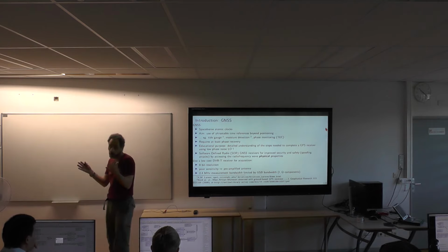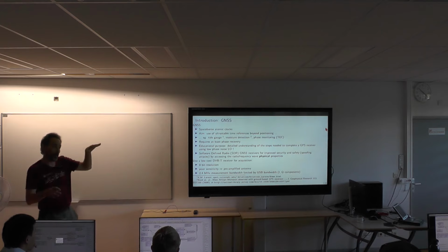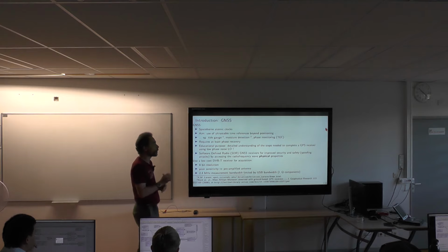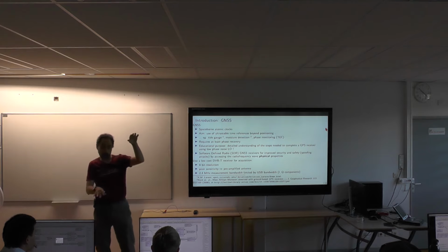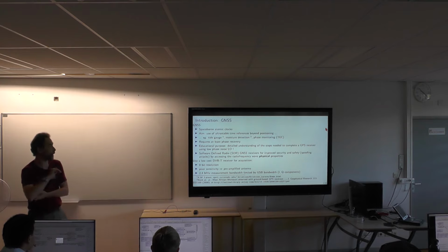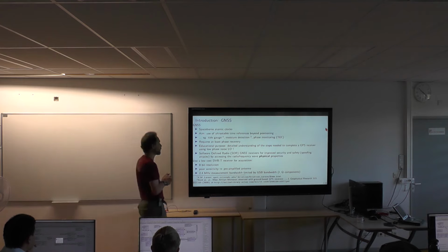And finally, for example, when I'm monitoring glaciers in Arctic regions, people have been putting one antenna on the surface above snow and one antenna on the surface of a glacier, and the time delay between the two allows you to measure the thickness of a snow layer. So there's a lot of things you can do with GNSS beyond positioning and time transfer.